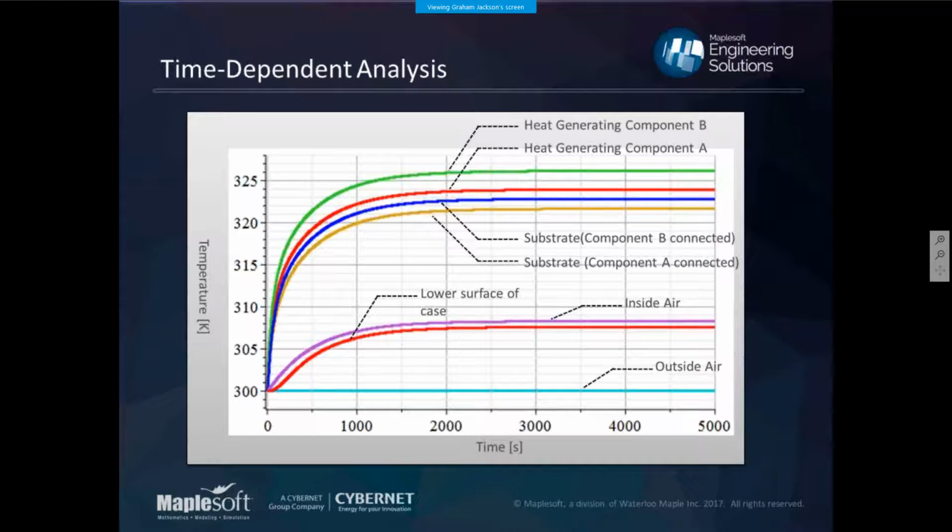You can see here that the heat generating part B is rising to the highest temperature, at 52 degrees Celsius. So let's say you knew one of your design requirements was to have a steady state peak where no part was over, say, 50 degrees, you'd see a bit of a problem here. So these are things you can spot early, and then you can start to design around.